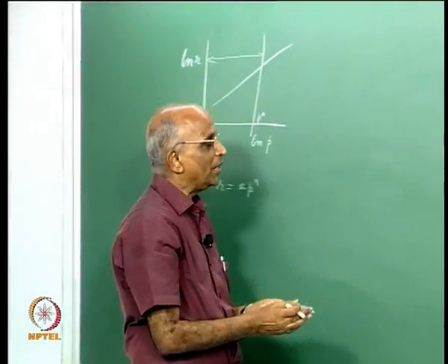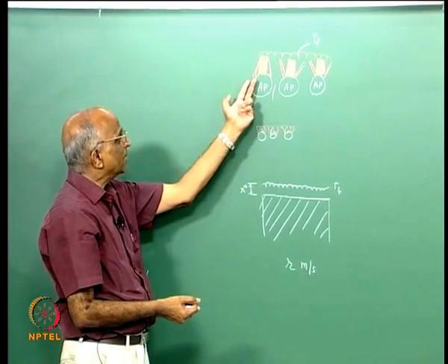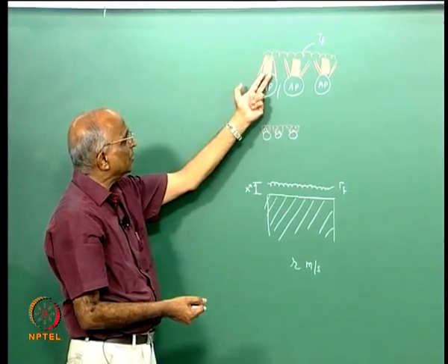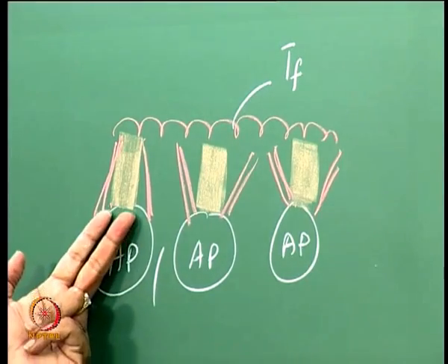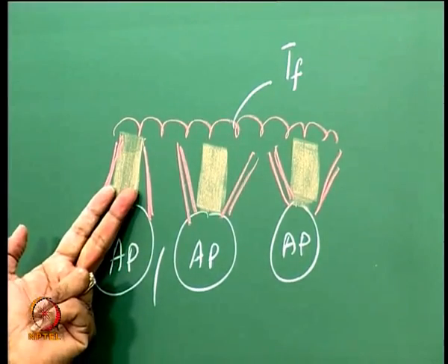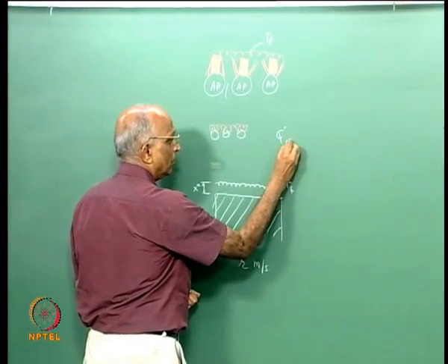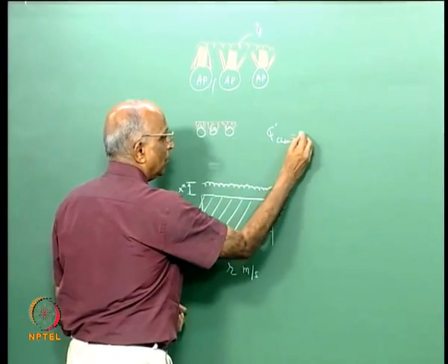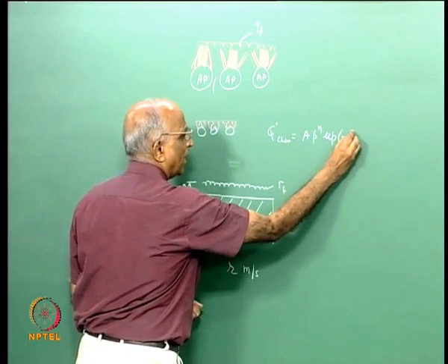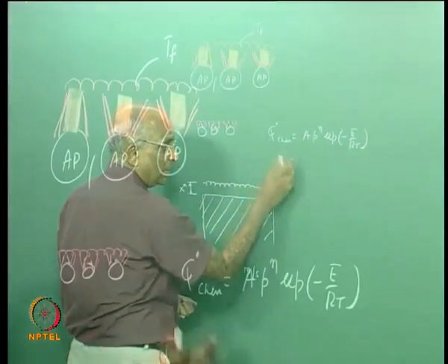What happens at low values? Maybe AP will decompose, but then the hydrocarbon vapors are coming, and the rate of decomposition at low pressures is somewhat limited by the kinetics. Why kinetics? We always write q dot chemical is equal to maybe A P^n exponential of minus E by RT, and this is the small q dot chemical per unit mass.